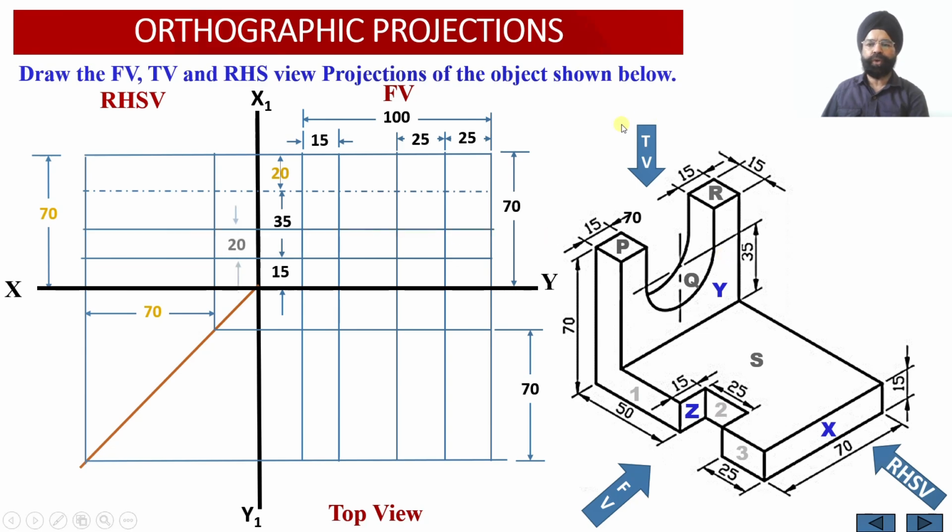Now the next thing we want to do is, please check, this radius is equal to 20 millimeter over here, because from this center we have a circular portion of this particular slot, which measures diameter equal to 40 millimeter, so the radius of this arc or circular portion happens to be 20 millimeter. I have been able to obtain the bottom point, that is the base point of this arc, by constructing another projection line at a distance of 20 millimeter from this center line, right?